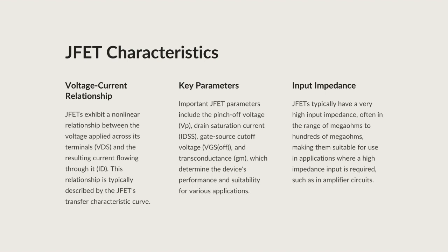Input impedance. JFETs typically have a very high input impedance, often in the range of megohms to hundreds of megohms, making them suitable for use in applications where a high impedance input is required, such as in amplifier circuits.